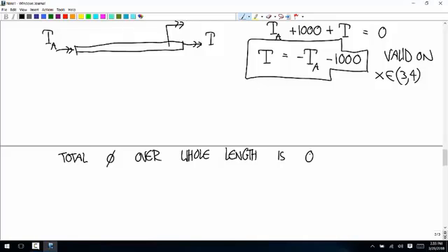And we have piecewise constant internal torque, so we're going to use this formula that says the angle of twist is equal to the torque, the internal torque on the first part, times the length of the first part over G times I sub P, and then plus the internal torque on the second part times the length on the second part divided by G times I sub P.